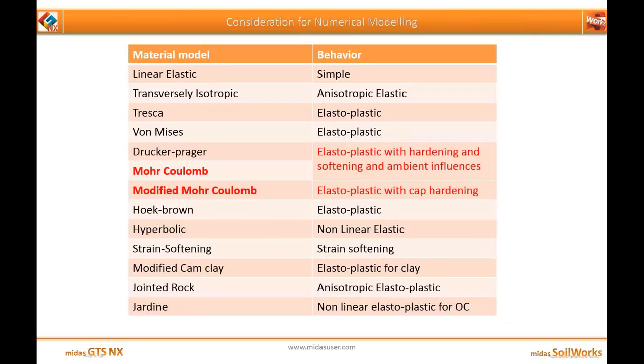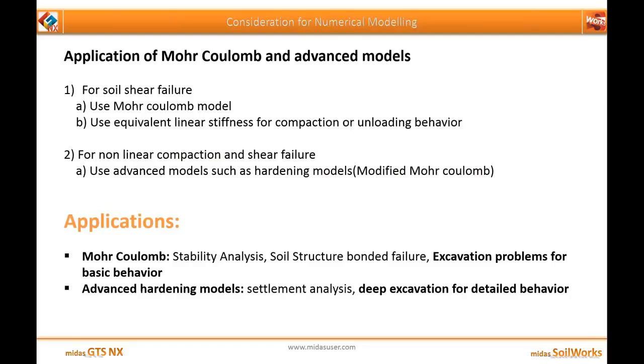Now the next thing one should consider is the constitutive model. MIDAS provides various constitutive models, but here I have highlighted two, Mohr-Coulomb and modified Mohr-Coulomb, which are more often used for shoring excavation. Also, if you are dealing with clay, you can use advanced hardening models like modified Cam-Clay.